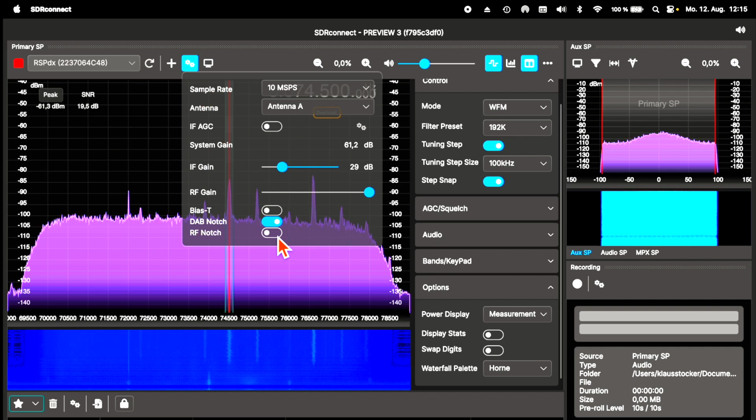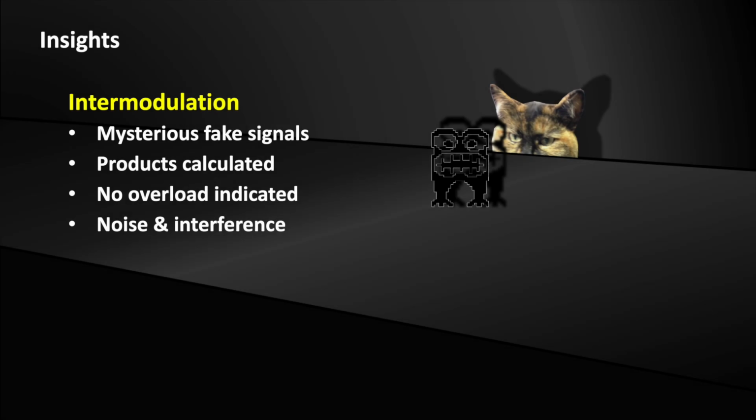Incidentally, digital systems are suffering from intermods just as much as analog ones. However, the signals are not mixing up on the data layer, as the receivers can no longer decode the mixed signals. So you won't see mixed videos or so. Using the methods proposed in our video series, you can estimate suspect signals to identify the root cause, and you can try the measures proposed to avoid interference.